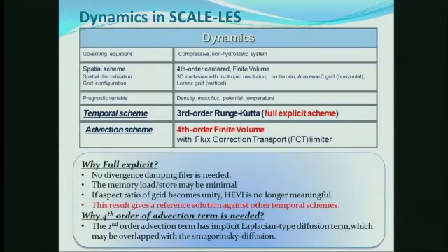So why full explicit? Full explicit has no divergence damping, so no divergence damping filter is needed, because there is no split of time delta t. And also maybe the memory load and store is minimal.